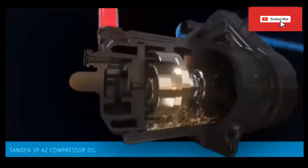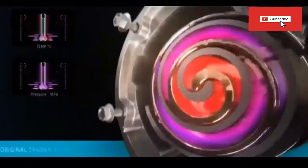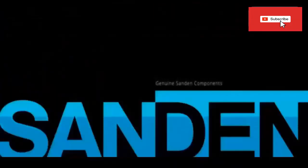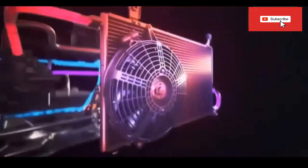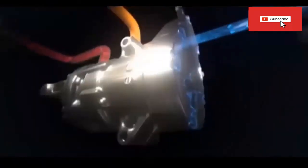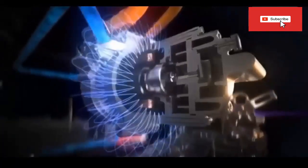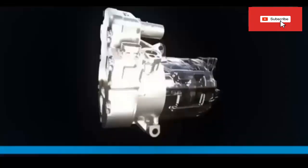7. Automotive electric scroll compressor. A. They use an electric motor independent of the vehicle's engine to drive the compressor. B. The motor is brushless, which uses a permanent magnet as a rotor and a coil for the stator. C. It requires an inverter to drive the motor. D. The inverter converts the direct current from the battery into alternating current for the motor. E. The air conditioner controller sends compressor rotation speed signals to the inverter to control the rotation speed of the electric compressor.